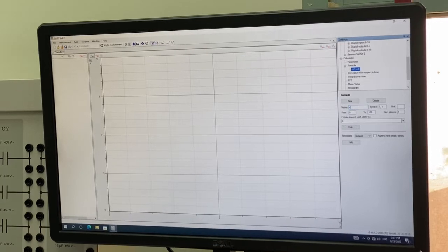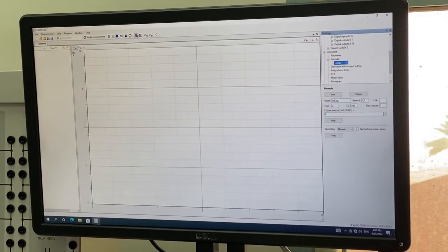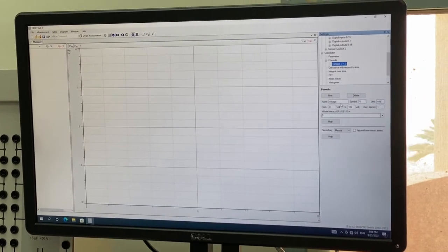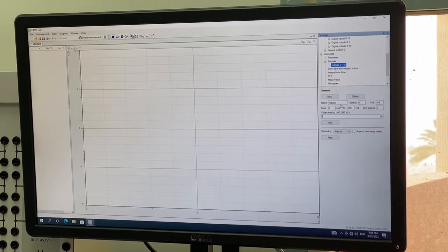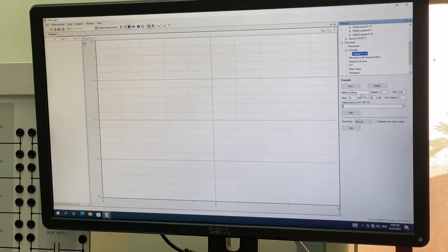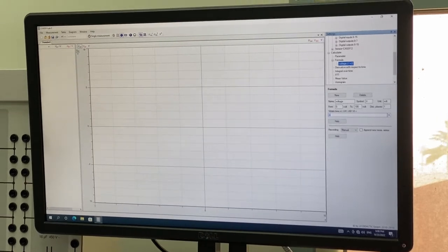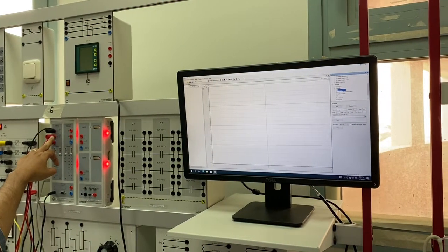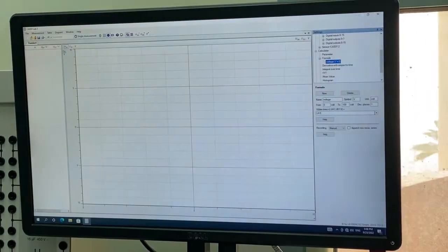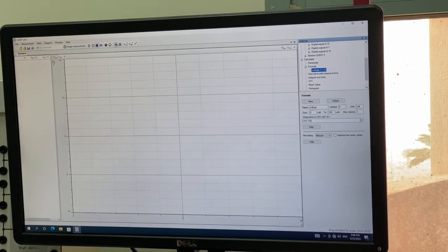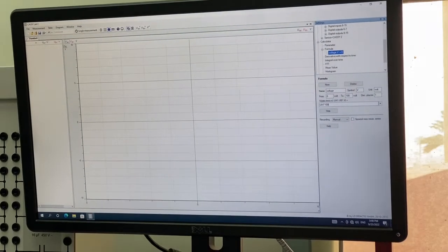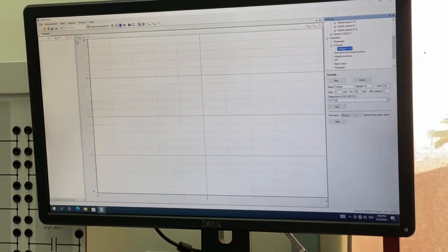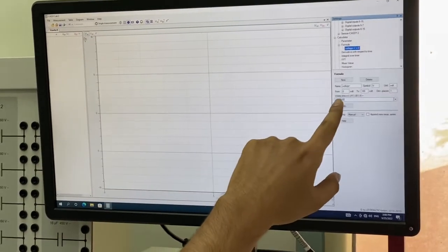Okay. So voltage, symbol is V, unit is volt from 0 to 100. What should be the formula for the voltage? The first one, right? So that means UA1, isn't it? Because the name of channel A is UA1. Why do you need to multiply with 100? Because over there you're supposed to divide by 100, and here it should be 1. So for the voltage we divide by 100 there. That's why you need to multiply with 100 here.